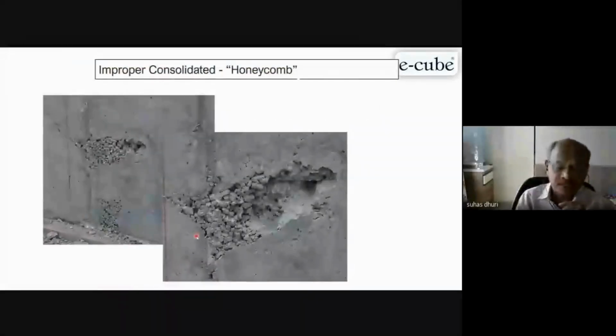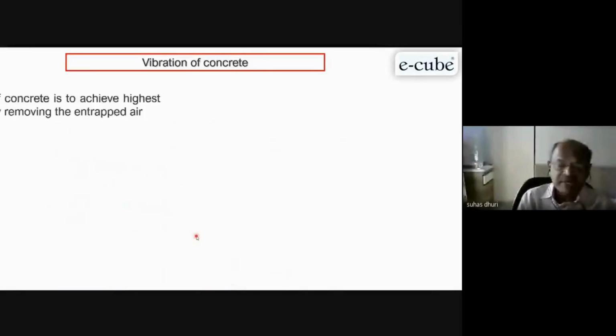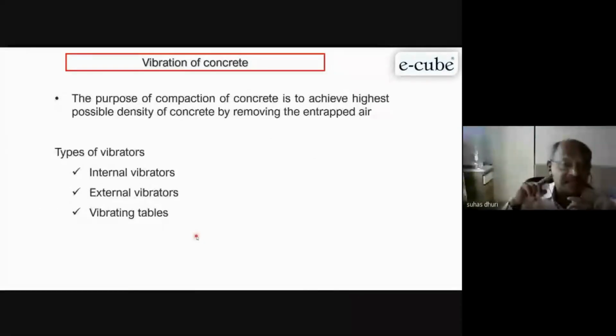Now this frequency of vibrator, I think we had discussed when we were talking about compaction in that particular VB test, where they give what frequency is there and what amplitude is there for the vibrators. So whenever we are selecting a vibrator, you must see what their frequency and what their amplitude is. Depending upon your structural member size, you select the appropriate size of vibrators.